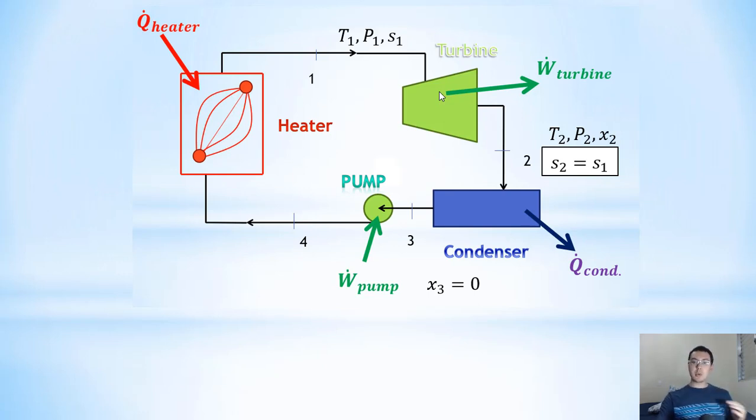If you look at any thermodynamics table, to calculate the entropy and the specific volume, we use the vapor quality, and we also know that the pressure at point 3, at the outlet of the condenser, is the same as at the inlet of the condenser because this process occurs at constant pressure.